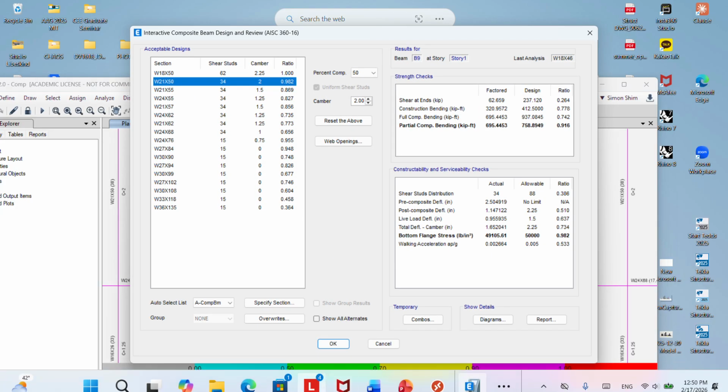So this is the end of the class today. ETABS chooses the applicable member sizes. Among the auto selection, this beam is all working, from the lightest member to the heaviest member, right? So 21 by 50 works, 21 by 55 works, obviously heavier, and a deeper 36 works, because they're all in our auto selection properties list.